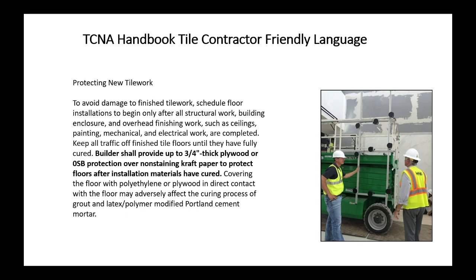So that's important. It also goes on to say you shouldn't put polyethylene or visqueen over a tile floor and then put plywood on it, because in the case of cement grout, that moisture is going to leave. It's going to get trapped underneath the visqueen and continue to drop on the joint till you have one very effloresced floor.